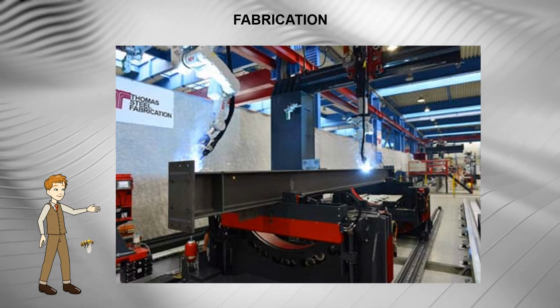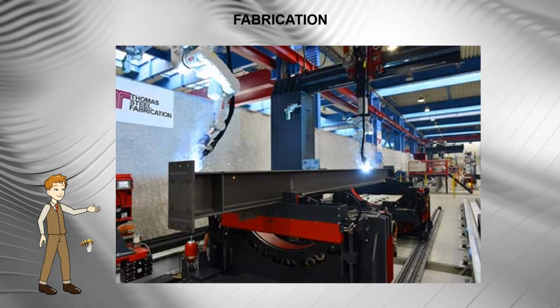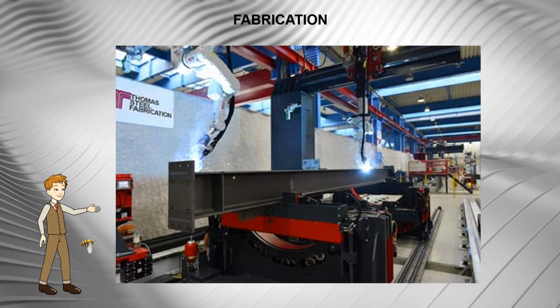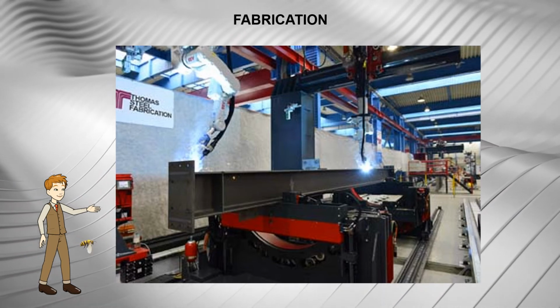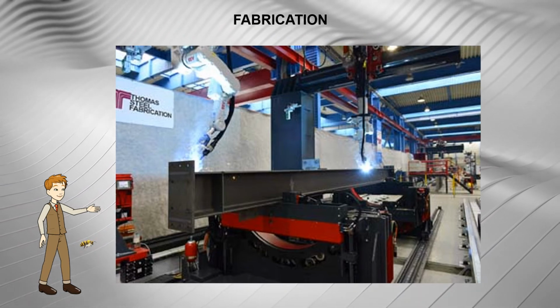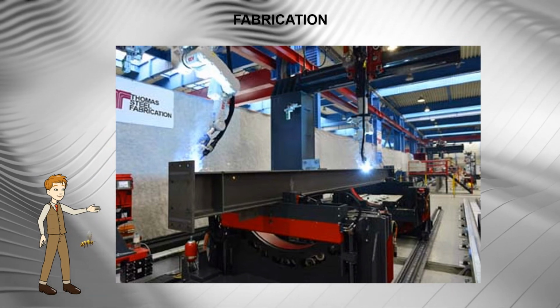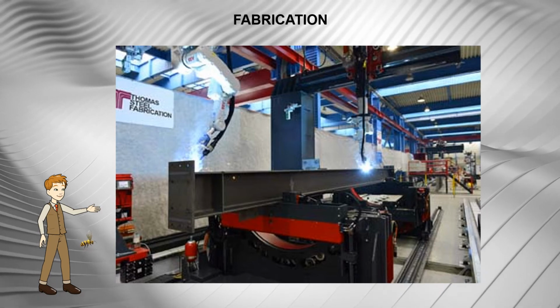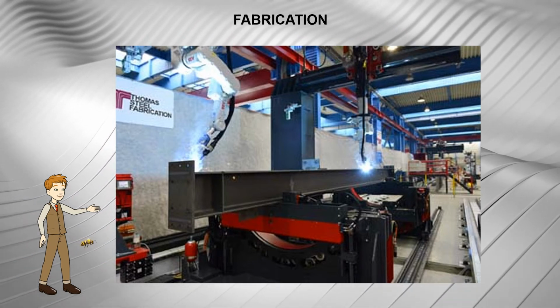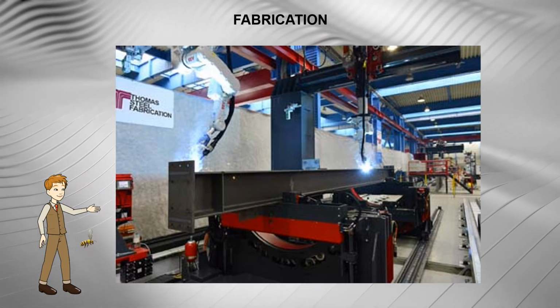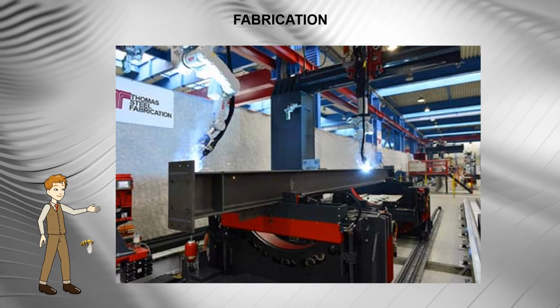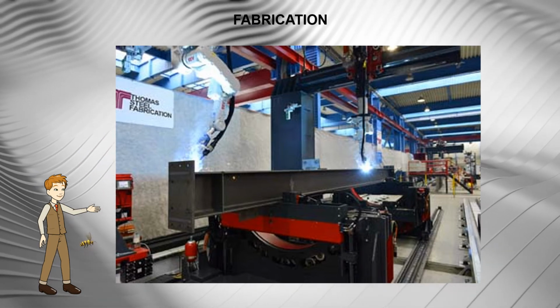It is essential that the design engineer notes that: number 1, bulk orders of minimum size variation are cheaper than small orders of many different sizes. Number 2, the number of pieces to be handled should be kept to a minimum. Number 3, weld distortion and tolerances should be allowed for.